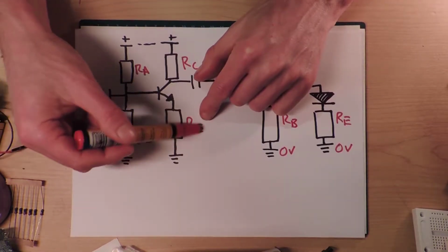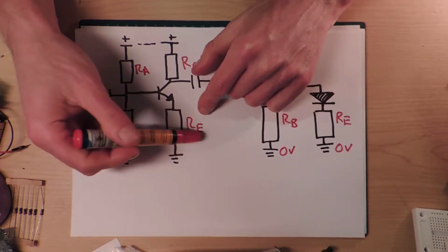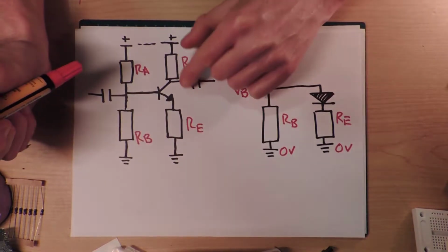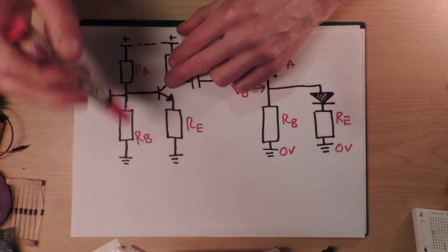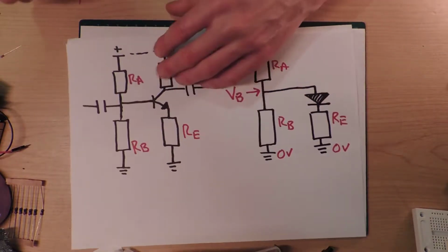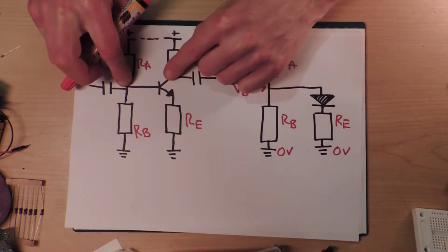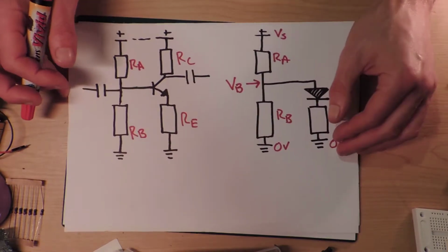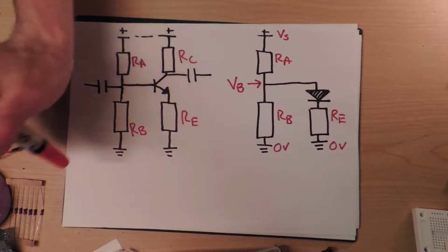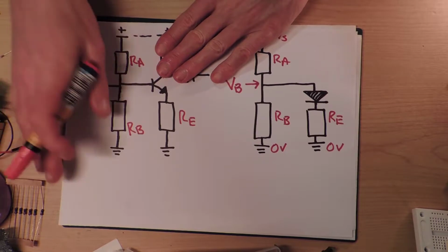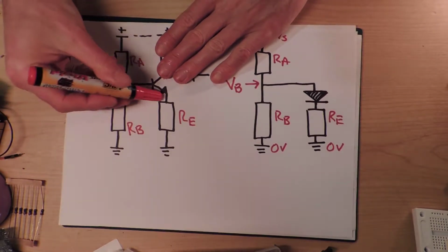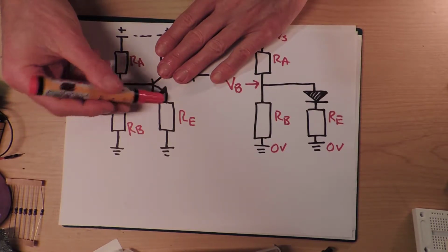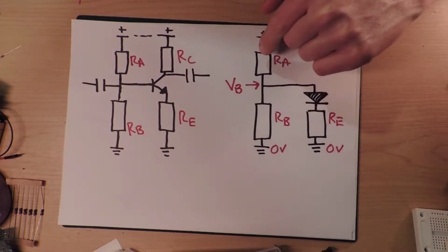So it does matter what the resistance of the emitter is, or the emitter load, if you want to work out what the voltage is at this point. This entire video is going to be about me trying to work out what the voltage is at this point, but I'm going to keep it simple. So I got kind of obsessed, well, let's just ignore the rest of the transistor and the rest of the circuit. We're going to ignore all of this, and we're just going to treat the base to emitter junction as a diode, in which case you get this kind of circuit here.